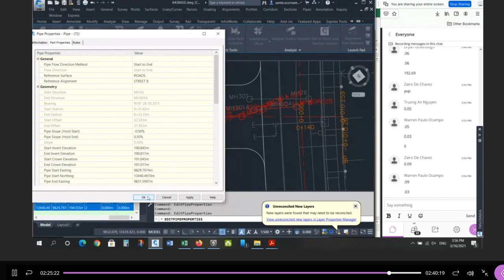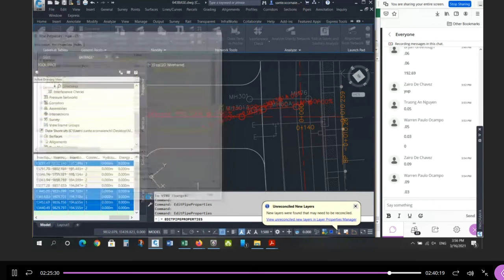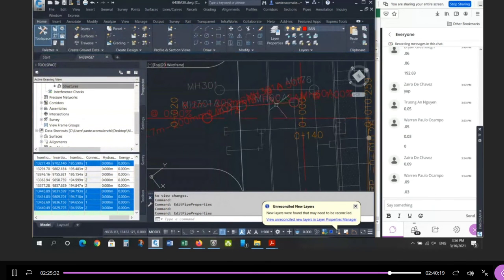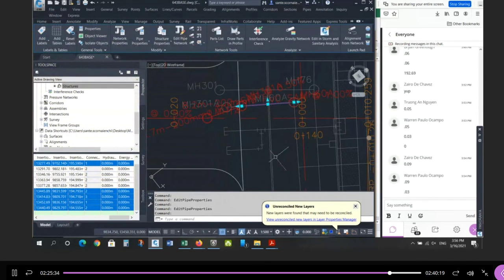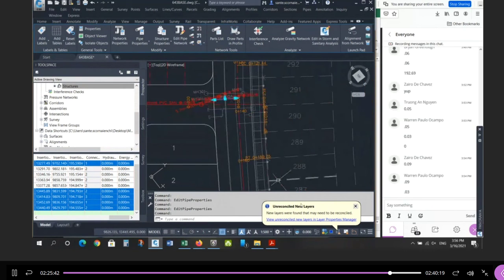There's one more to do, and I'm going to actually determine the values of the inverts and the slope based on it's an existing pipe. So let me show you that. So I'm not designing these inverts for this existing piece. It's already in the ground. So now I want to look to ledger way to find this invert, and I'm going to go whatever the slope is. Okay, so let's go look at ledger way.